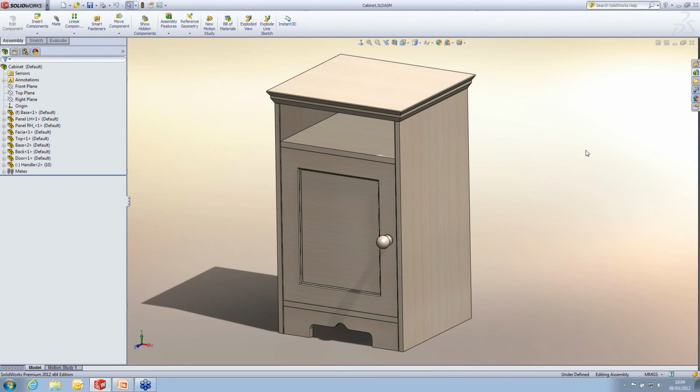Just got this camera opened up and I'm going to use this within the first part of the webinar. I'm going to build up a smart component. For any of you who haven't used smart components before, they're a really quick and easy way that we can group assembly components and features together into a little group so that we can insert them into loads of different models. So it really does speed up your assembly modeling. In this particular example, I'm going to take a cam lock, which I'm going to put in and assemble in place, and I'm going to show you how to create a smart component from that.